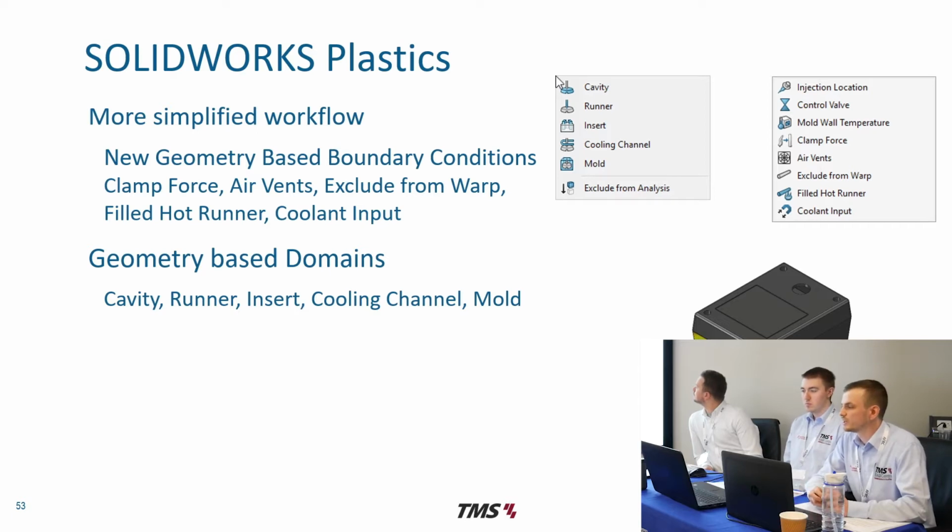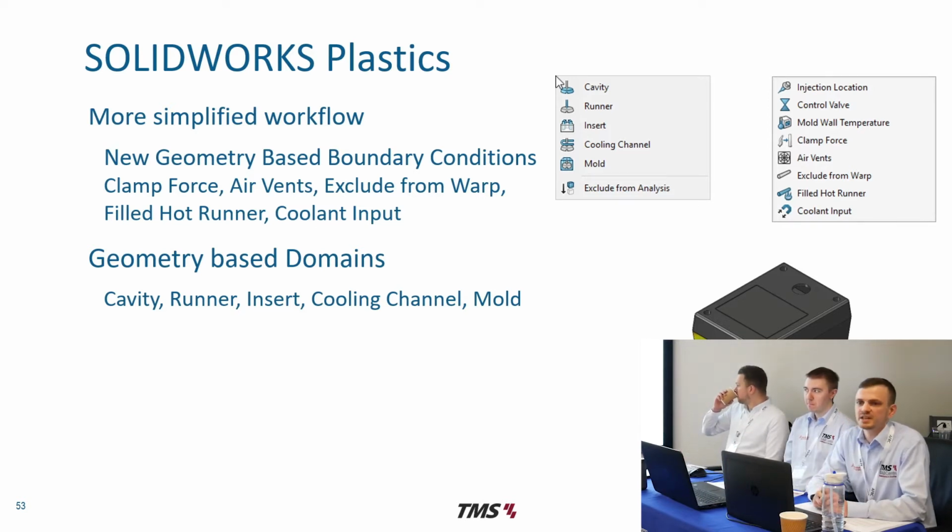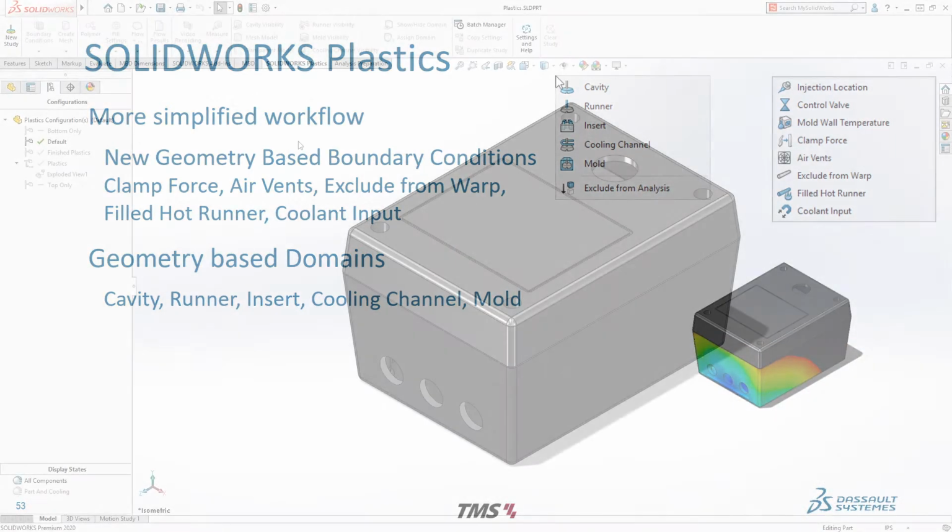Now again, with 2020, there's some great new enhancements with this one. Up until 2020, we'd always have to mesh our model before we go ahead and define any of our domains or boundary conditions in there. But now we can go ahead and apply these directly to the 3D model. Just to see this a little bit better, again, it's a little example.